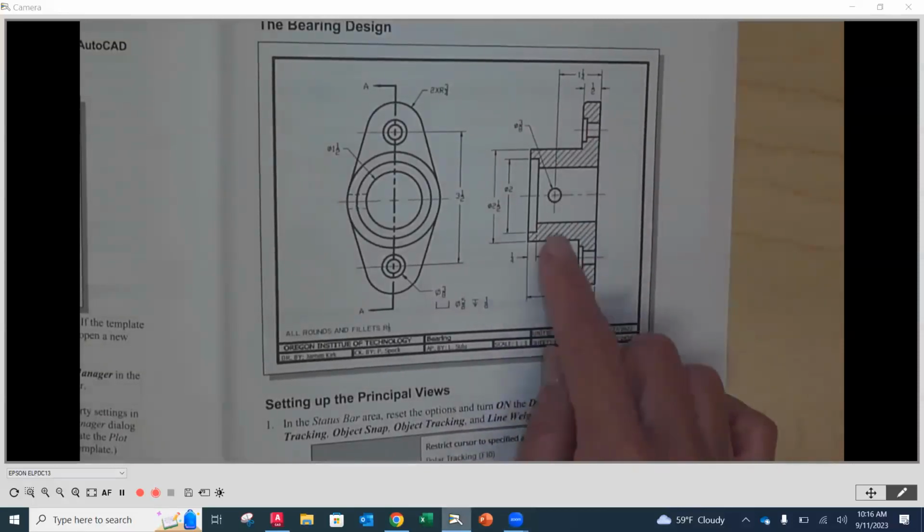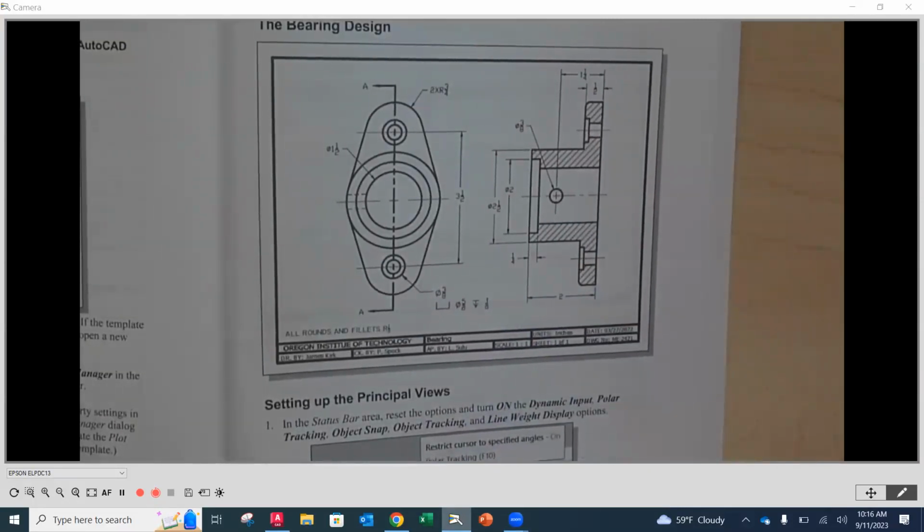So we've got the perimeter around here now. Now we've got to work on those inner parts. Remember, these are going to be solid lines now, not hidden lines, because we're going to be doing the full section right away. So I'm going to start with my counterbore holes right here.